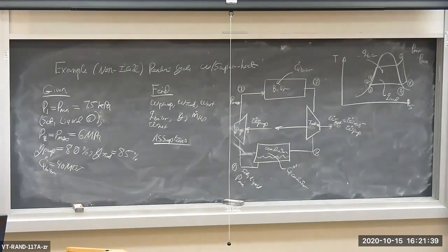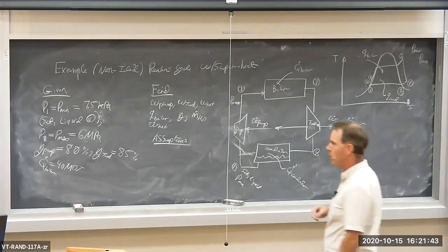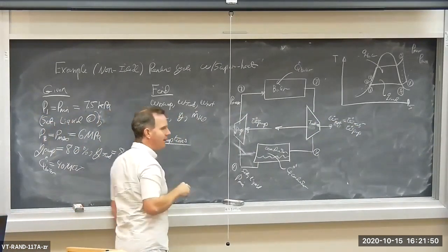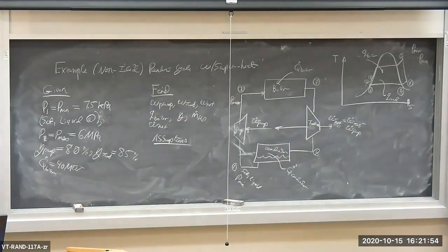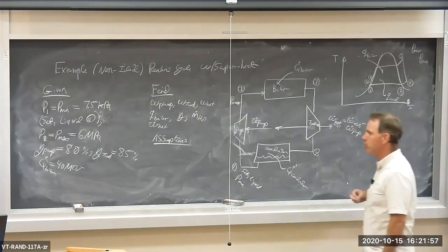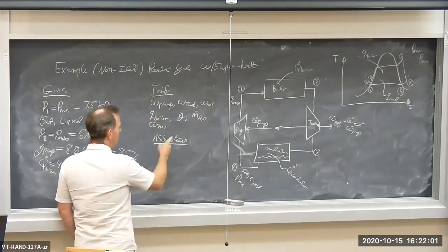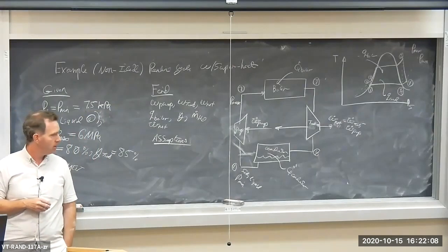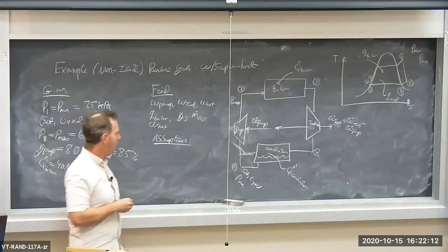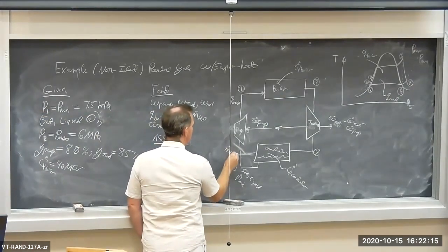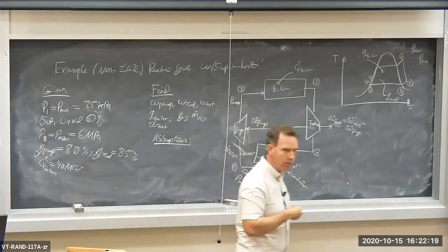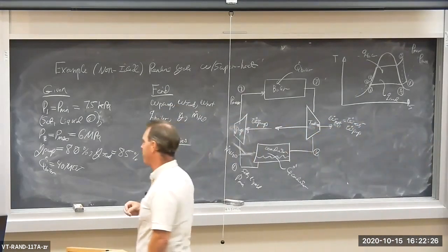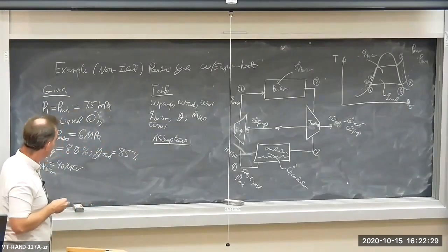40 megawatts. So what are we supposed to find? Let's find the specific pump work, the specific turbine work, the net specific work, the specific heat addition, Q boiler, into the boiler, and the thermal efficiency for the cycle, so W net divided by Q in, or Q boiler. Find the mass flow rate. What's the actual mass flow rate? The rate at which H2O flows around in the cycle. And then we're going to calculate the total power produced, the net power produced by the cycle. Okay? So that's the plan for today.